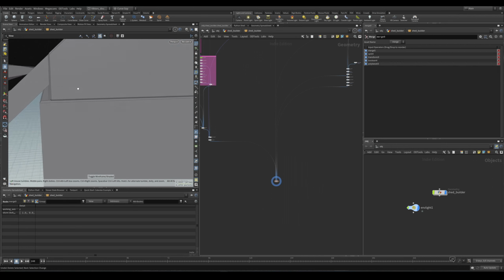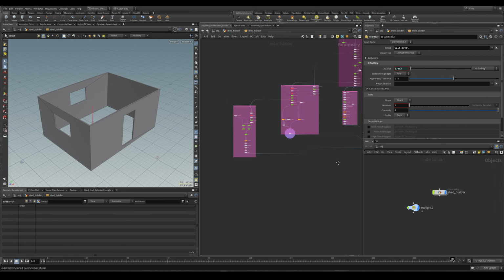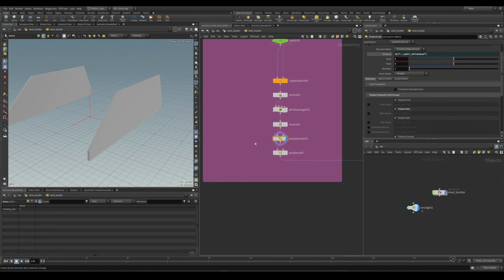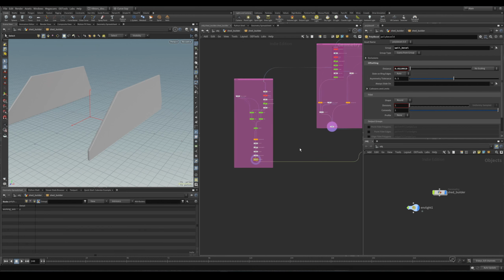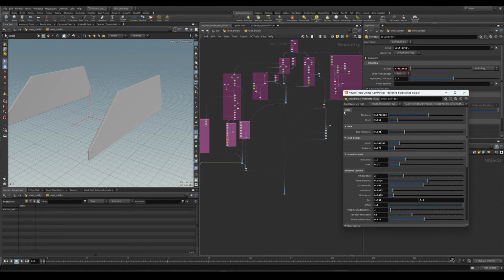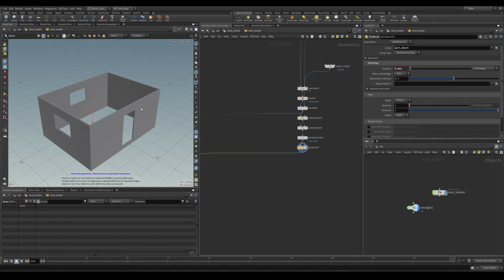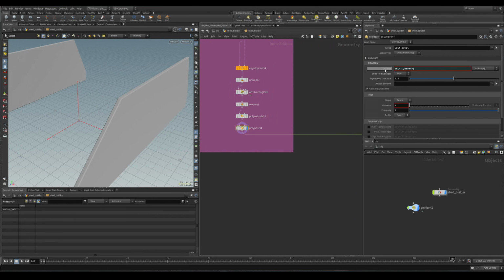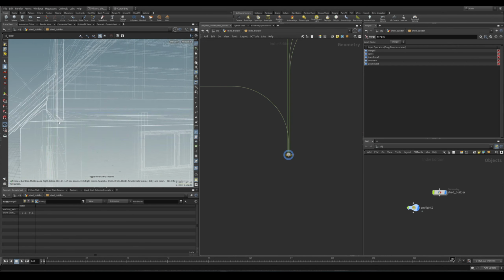And to add the bevel for our trim, all you have to do is copy this poly bevel for our wall and paste it inside where we extrude our gable, and add the same poly bevel node, like that. And then you can just go ahead and add this to our HDA parameter. So under the wall controls, we have a bevel amount. Just copy the parameter. I have this already linked up to my wall. Just go ahead and also link this up to our bevel inside here, like that. And at the end of it, you should get the consistent bevel between the edges, like that.